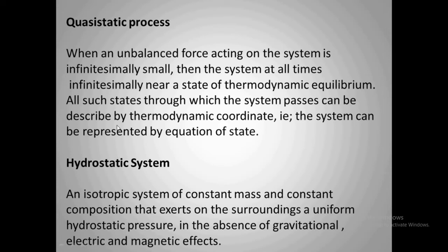So what is the definition? When an unbalanced force acting on the system is infinitesimally small, that is, a very small force, then the system at all times is infinitesimally near a state of thermodynamic equilibrium. So all such states through which the system passes can be described by thermodynamic coordinates. That is, the system can be represented by an equation of state.